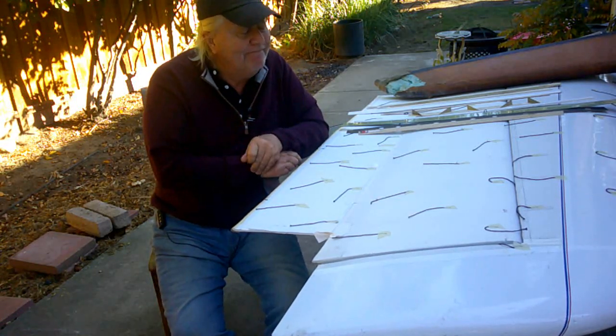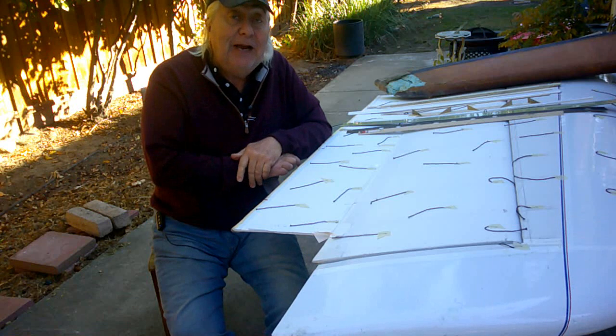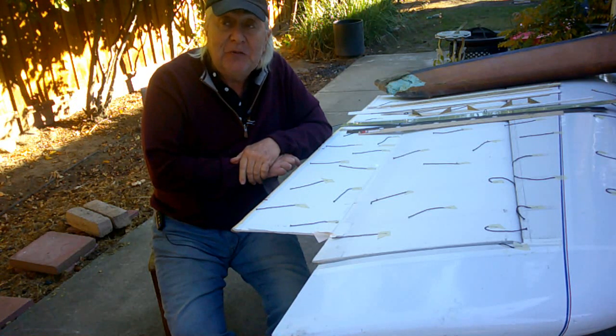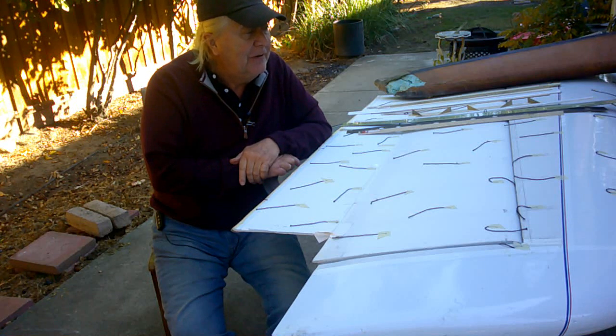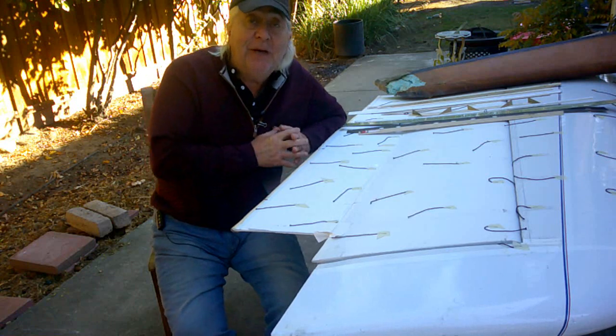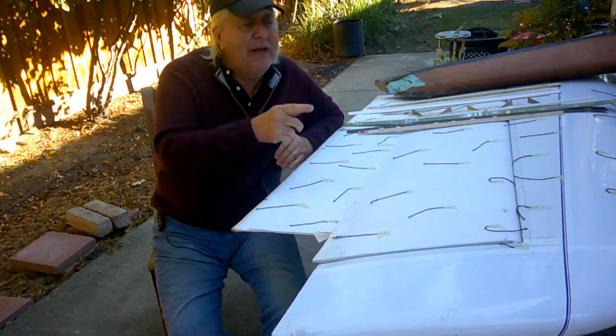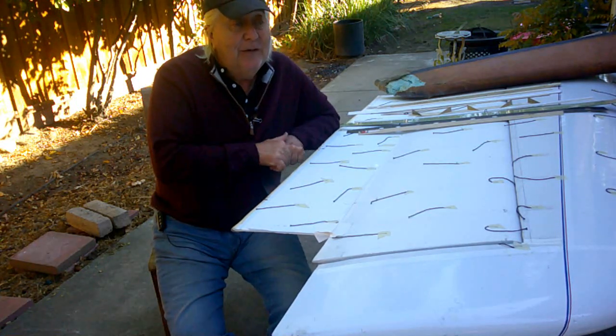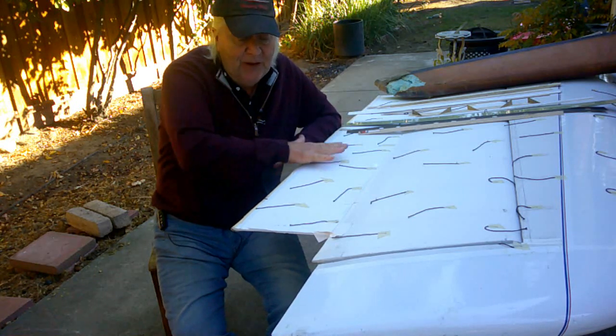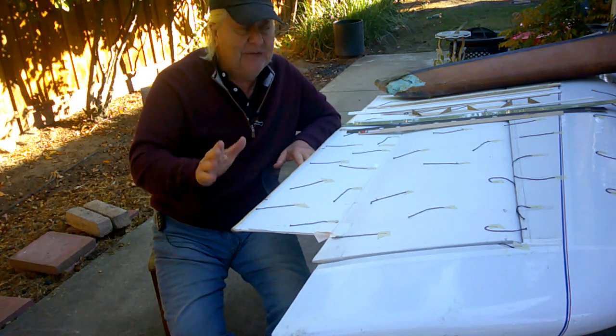Okay. Interesting. So, hang gliders, wing warping, no problem. Plenty of control, no flow separation, no weird behavior. Okay. Yeah, but let's go back to my first wing. First wing, okay, a little higher Reynolds number, but I didn't have any of this weird spanwise flow when the elevons were down. Didn't have it.